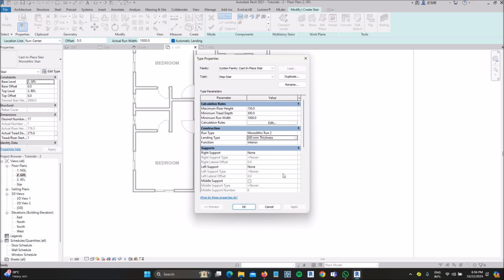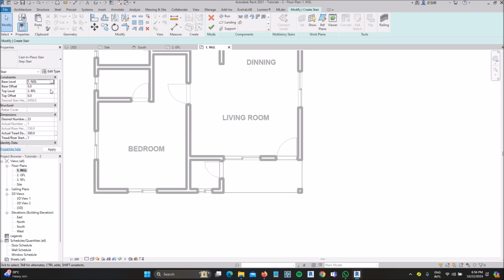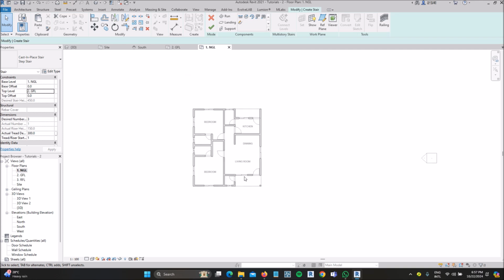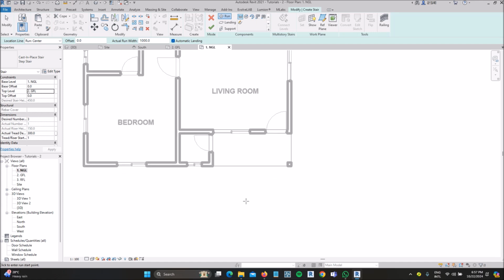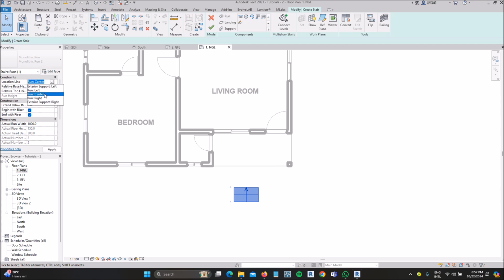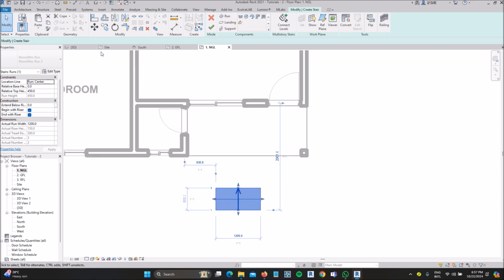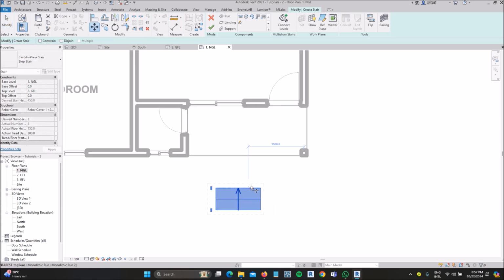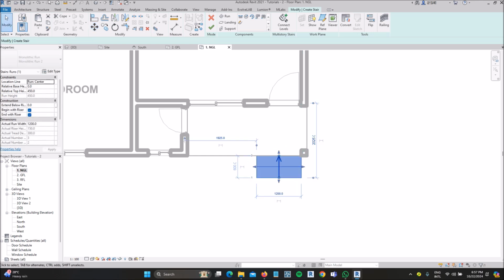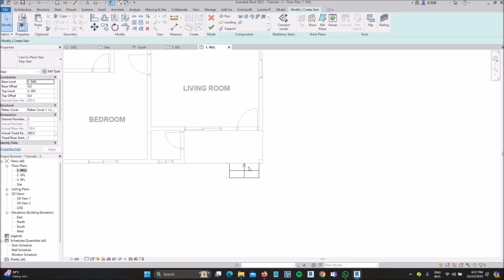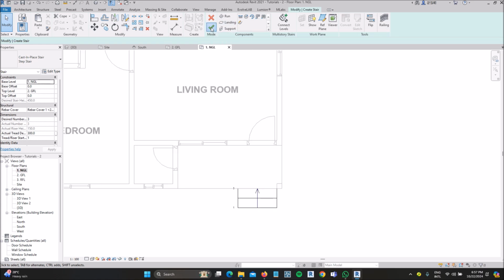I'll say first thing to note, my floor is starting from my natural ground level, ending at the ground floor level. So first thing to note, I missed that. Go to the natural ground level before you start the step, because the step is more like you are creating staircase. So from here, I run it like this. Just like you do staircase, you can change the thickness. Let's make it 4 feet or 1.2 meters. Let's bring it here. Okay.